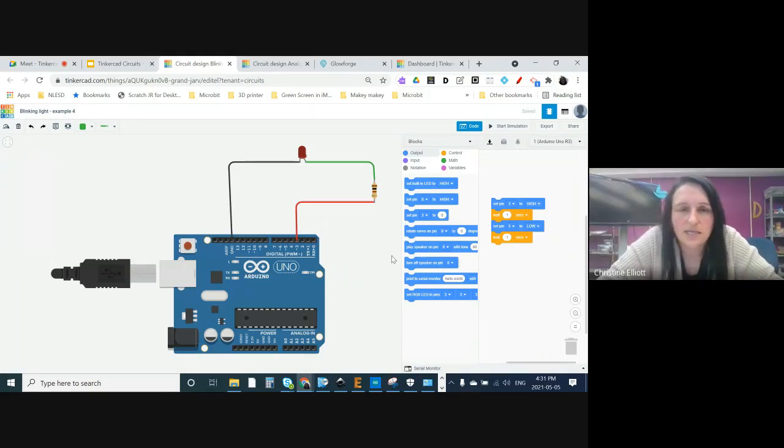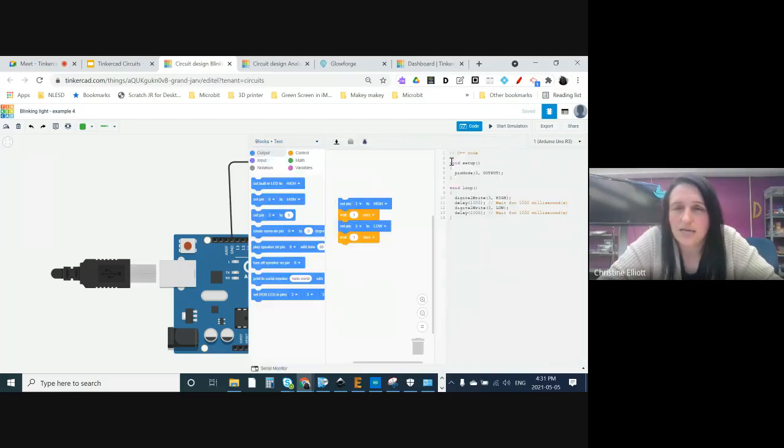Basically, you are just turning on or turning off one of these pins, as you can see with the code, and it makes sense when you look at the text, because this code is based on C++. You're setting up your pins here, and anything underneath void loop, basically, all that means is anything that happens underneath that is continuous.